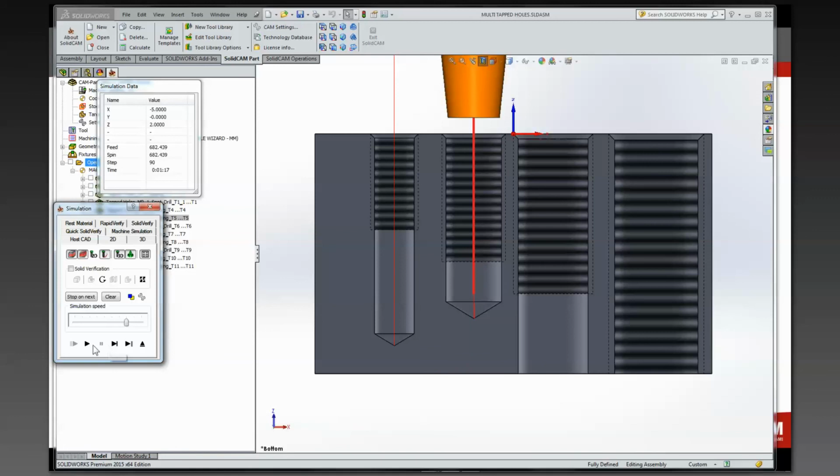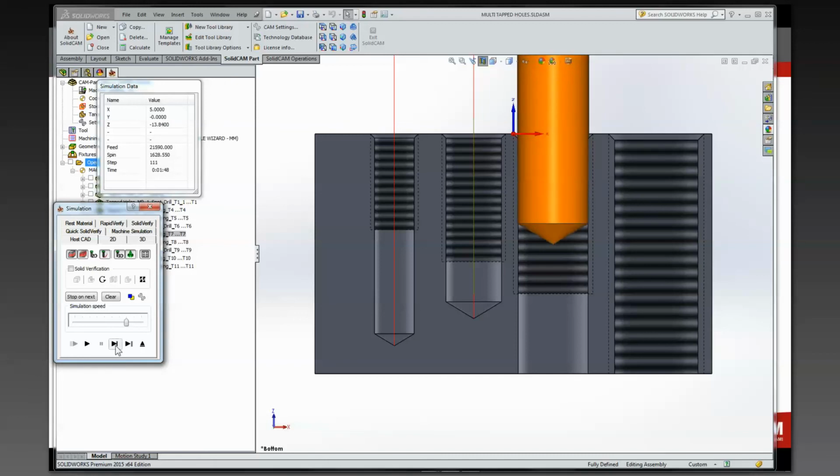Okay, some pretty cool stuff. Now let's go to the next one. Different size spot drill, took it to the right depth. Okay, let's walk this one down. It knows it's a through hole. So now it's going to go ahead and use delta to push through. User-defined amount.